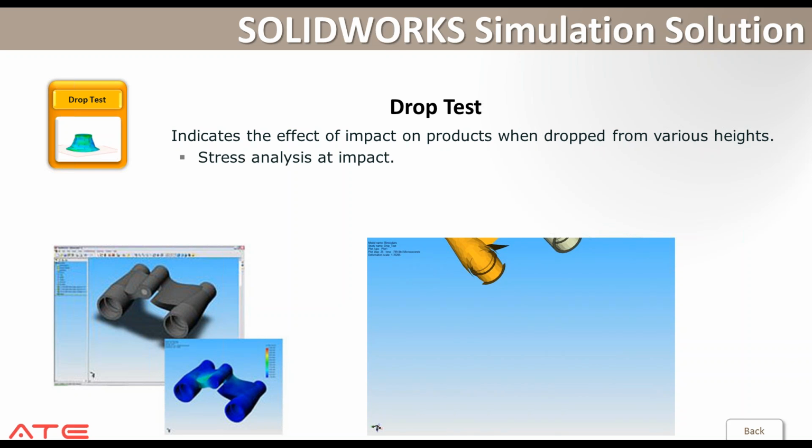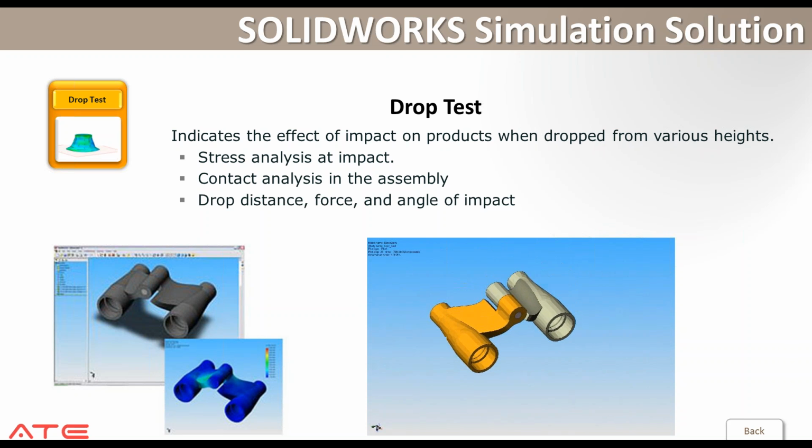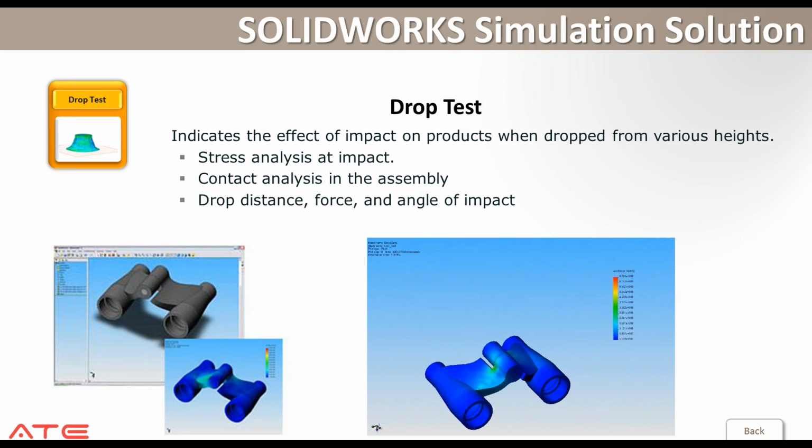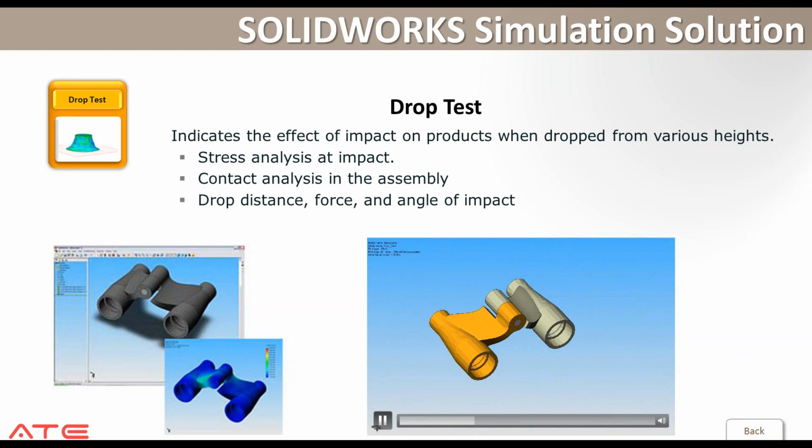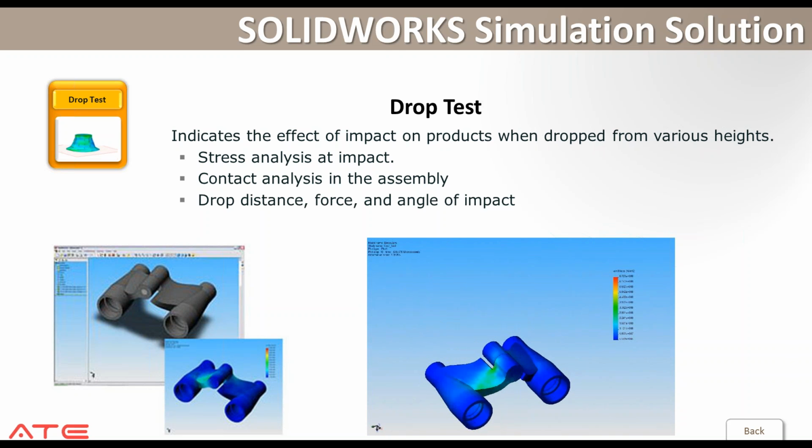So bear in mind that impact loads are considered as nonlinear loads or dynamic loads, as they are not applied slowly to the components. Then it can cater for the contact in the assemblies, and we can put in the drop distance, and we can put in the velocity value as well. Okay, examples will be on this. So simple calculations, animations, and we can capture every single moment after the impact.